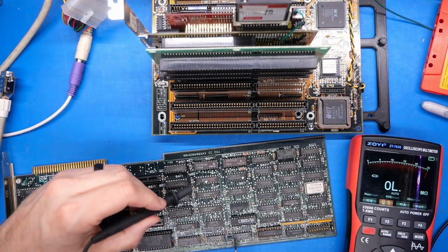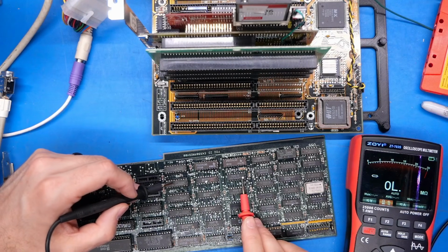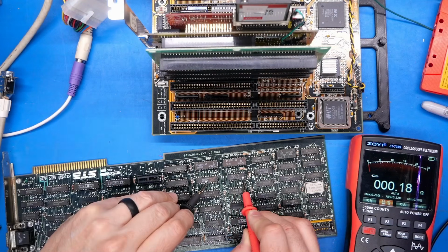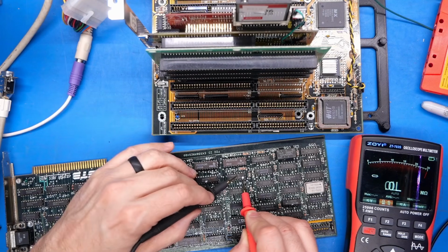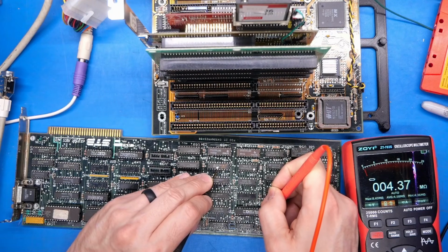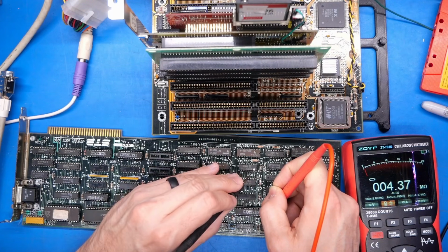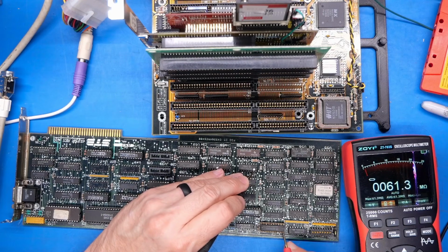As far as I can tell, the output of the flip-flop that's not working, which is this pin here with a white mark, makes its way to this chip here, which is a multiplexer, a 74F151. There we go, we have a dead short between these two chips, 0.12 ohms. Now I wanted to check to see if, say it's shorted to ground, 4.3 megohm. That's from the output pin here to ground. Now, I was thinking that if it was shorted internally to 5 volts, same.